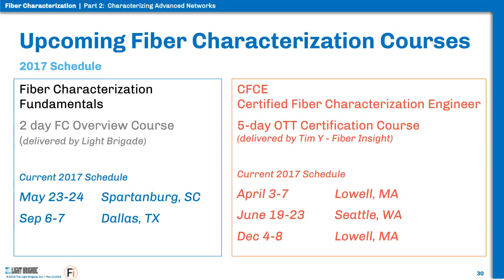As a general rule with G.652 fiber, if you do the math using your 16.5 average picoseconds per nanometer-kilometer, and you know that at 10 gigabits per second, assuming we're talking about SONET or SDH, you're going to have a CD limit of about 1,000 picoseconds per nanometer. That translates into a typical range of about 60 kilometers that you could go with that 10 gigabit per second signal.